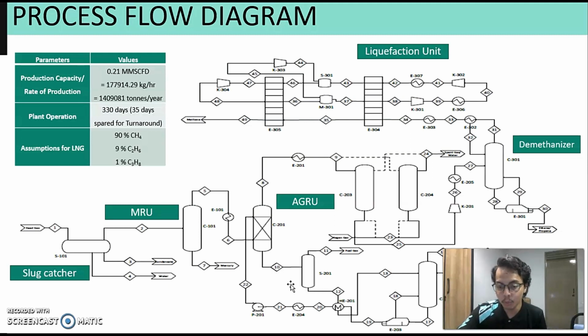That's when we will use a stripping column to separate the remaining natural gas to be used as utilities. The impurities will proceed to the distillation column, where we will regenerate the amine and separate the CO2 and H2S for other uses. And the amine, the DEA, will go back to the absorption column to be used for absorption.